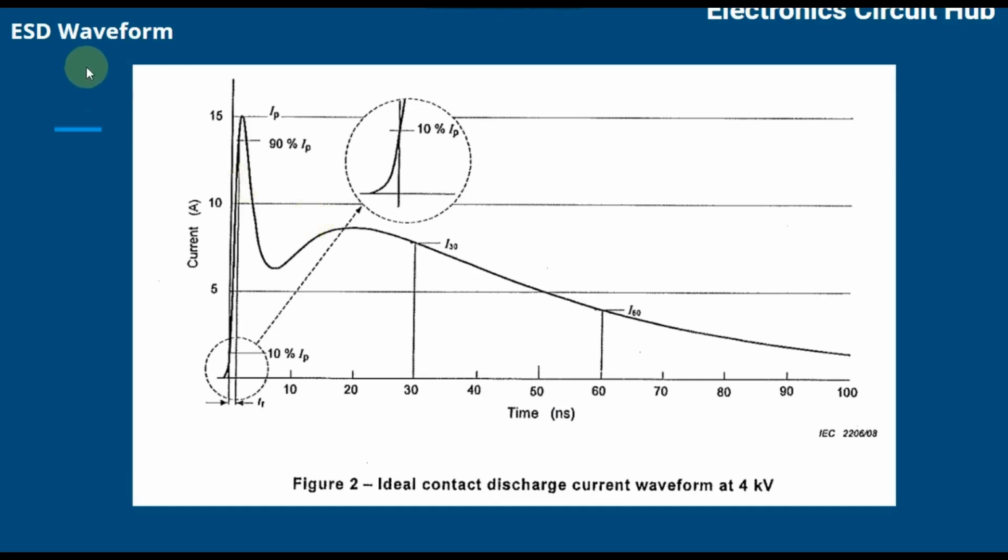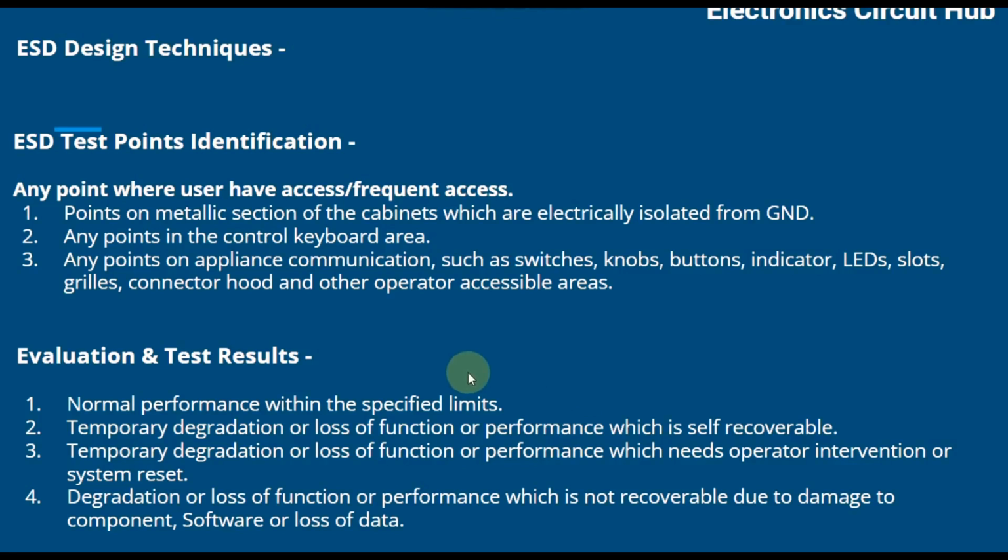This is the ESD pulse diagram or waveform. You can see the rise time of this ESD is less than 1 nanosecond, and the pulse width you can see here is around 60 nanoseconds. Now let us move ahead to the ESD design techniques.